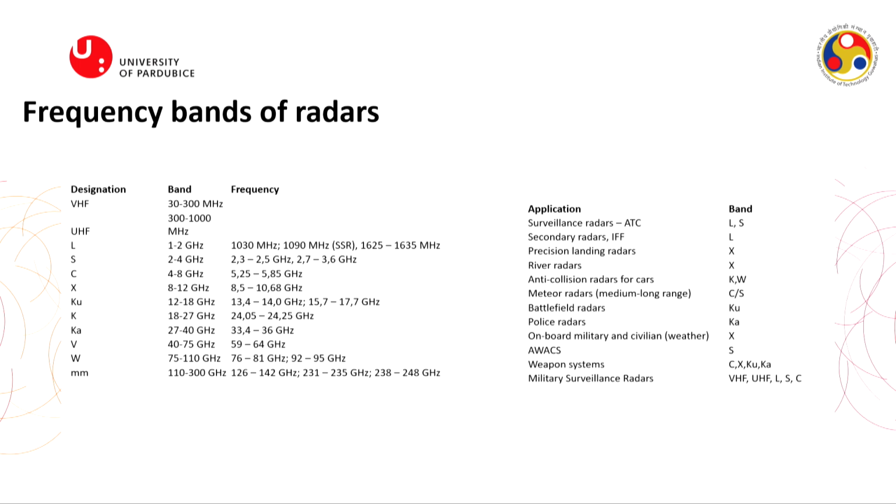Then we have automotive radars, and what do you need for automotive radars? Really huge resolution, because you want to detect pedestrians, children, I don't know, dogs, anything, something really small. So it is clear that if I want to increase resolution, I need to increase frequency. For this reason, automotive radars are in bands from about 40 up to 70 gigahertz, about 75 gigahertz, I think.